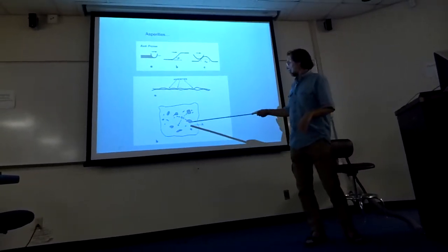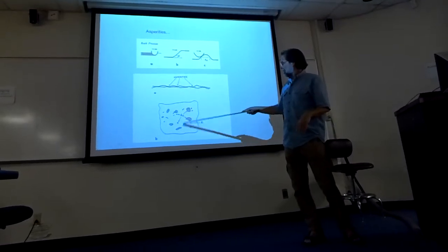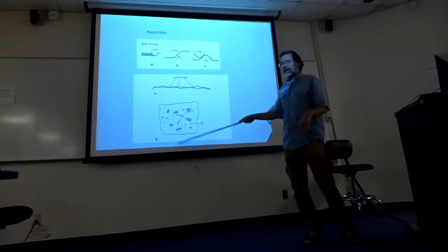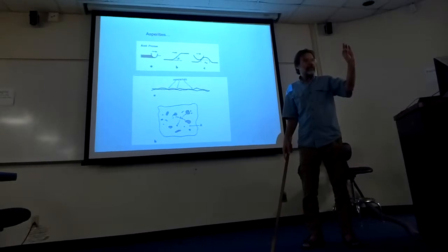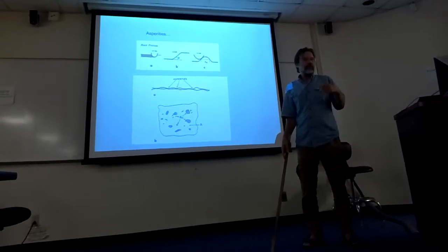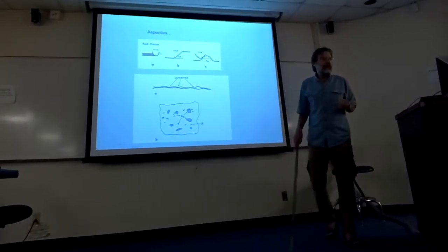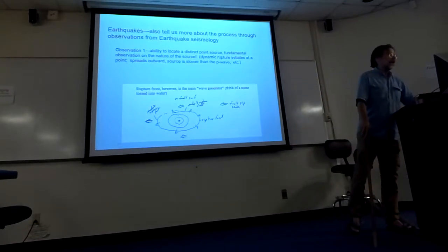That's the general theory of stick slip: if you can make a cascade effect, once you break down the biggest contact asperities, then it can move. And then you go into a kinetic mode that's different than the static mode.